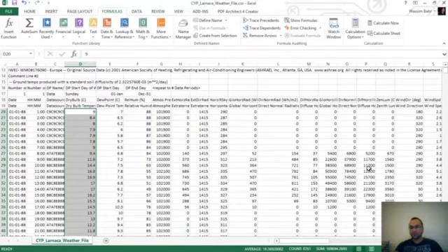In addition to this, you have as well the wind directions, for example. Sometimes we need to know the direction of the winds, especially if you are designing for natural ventilation. So here you have the direction for sure from north axis. It's not clear whether from north or south, but usually when we consider the azimuth angle, it's taken from north. So it appears that if it's from north, so 180 degrees from north, the prevailing winds direction, dominant or prevailing winds direction. And there are other data included in this weather file.